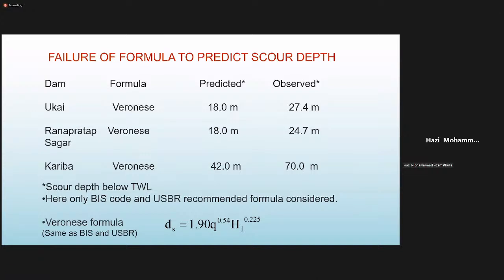Similarly in South Andhra Pradesh, Srisailam Dam, they made a blunder: the lip angle of the bucket, they put 30 degrees, so the jet is not going further. It's like due to turbulence the scour takes place. Another thing, due to this complexity, not many equations. No one has solved this problem.